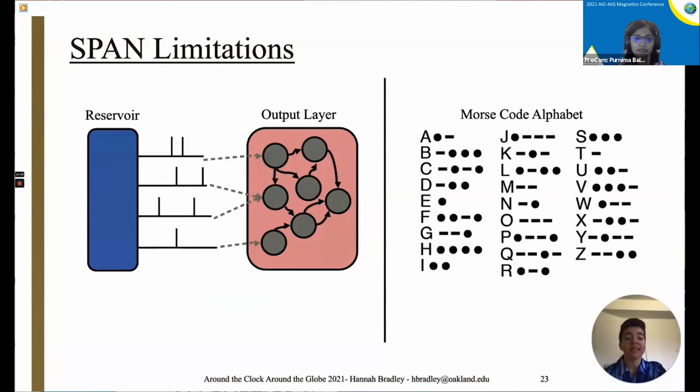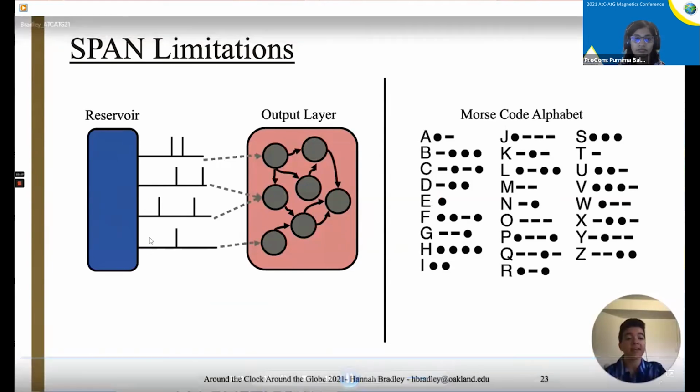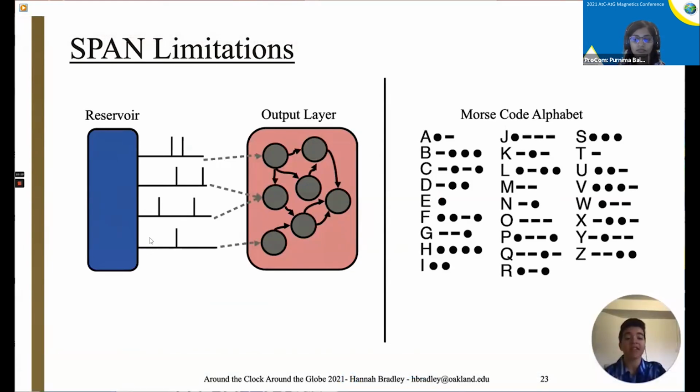We propose, instead of a simple one neuron output layer like SPAN, a more complex output layer capable of higher functions. We have previously investigated inhibition circuits and have found that they are easy to implement with AFM neurons because of their effective inertia. These types of circuits would be an integral part of the more complex output layer because they only used fixed weights.